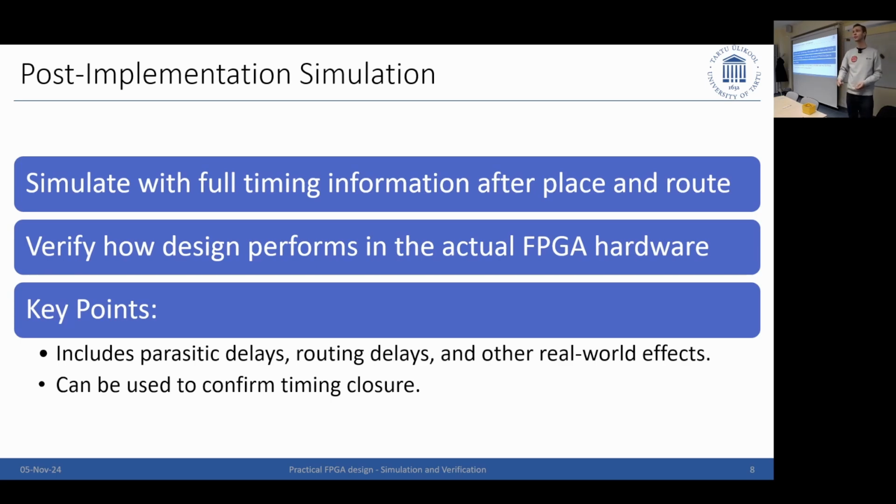I mean, not everything which can happen, but it simulates what I stimulate as input. So I give an input, and that propagates through my logic, and it will brute force the worst delays, parasitic delays, and so on. So if you want to put it badly, it puts a margin on the delay of the signal based on your design. And that, of course, takes extra time to calculate.